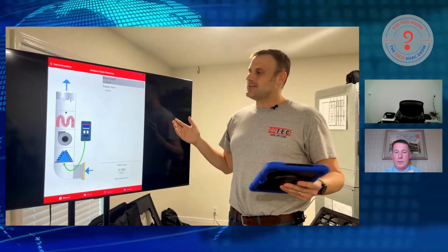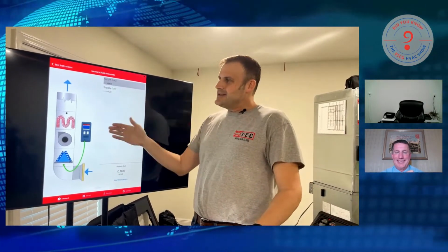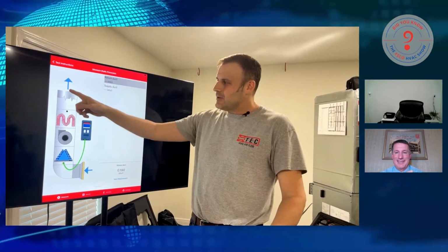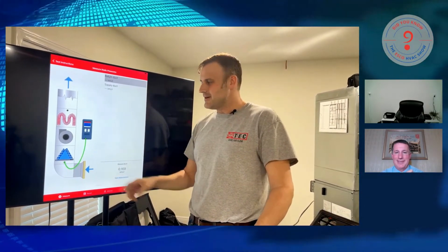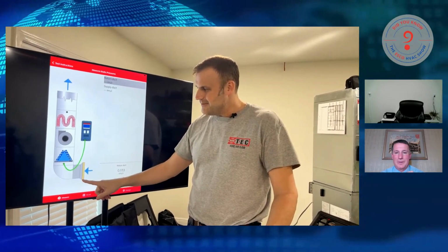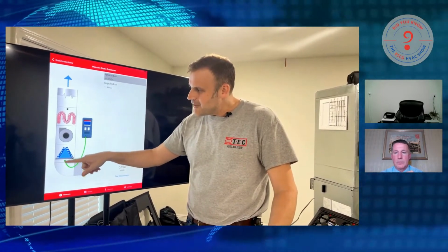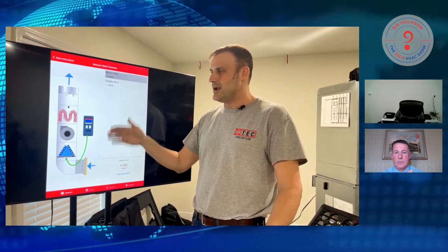Now we're off to the races. Here's what I love about this app. Every time you make those workflow selections, we will paint you a picture of the install that you just entered, right? Yeah. So you'll notice our filter is in the grill. If you select filter slot, we're going to rotate that picture and put it right here. And we have those dots, right? That's showing you where to put your static pressure probe when you're taking these measurements.